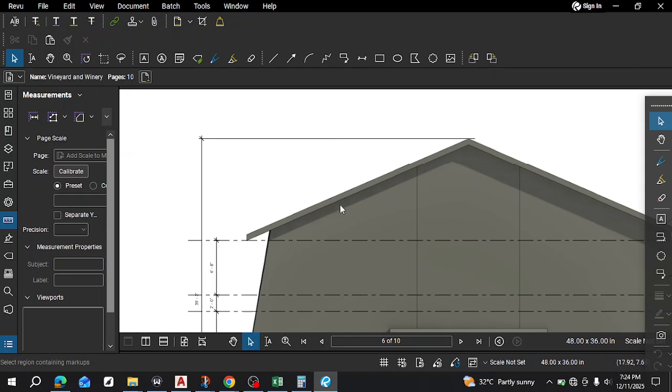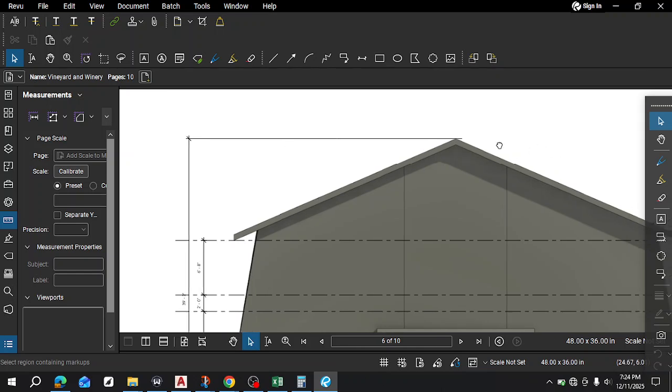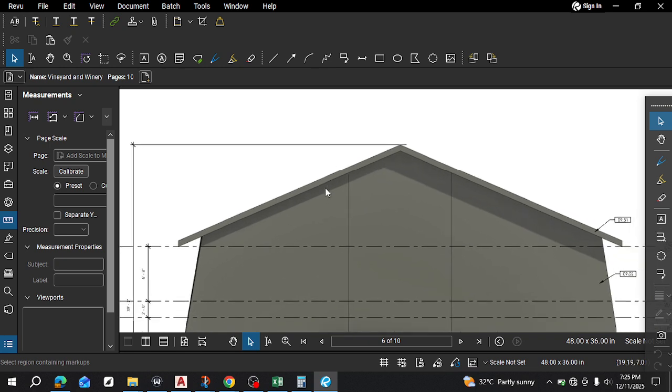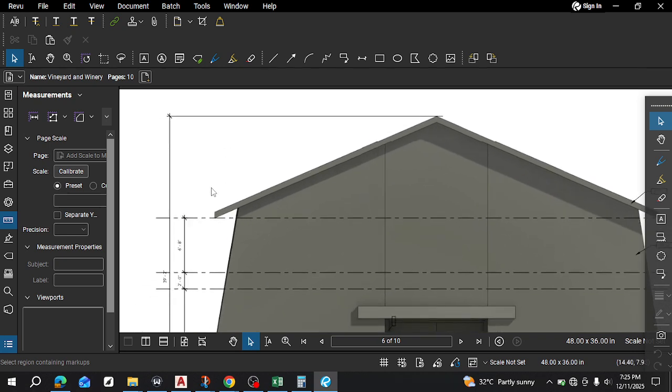So let's take half of that distance, which should be closer down, because we want to assume that this is a rectangular wall, right? If taking this as the height would mean that the wall extends all the way to here, but that's not the case. So let's take half of it, because if you divide this space into two, this is about a triangle that makes half of this rectangle. If you take half, it should give us a value as accurate as possible. So half of this height is 6 feet, because this is 12 feet.